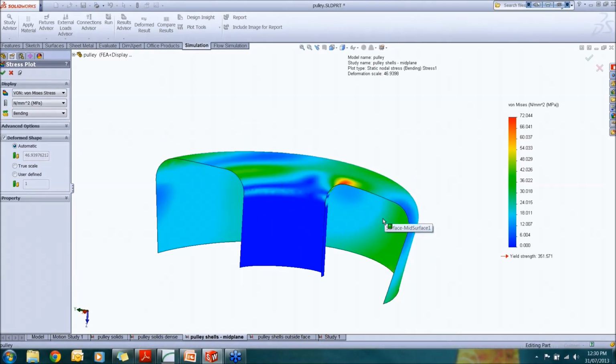So simply, we have put our shell elements somewhere in the middle, and the software calculated the stress values on the top face, bottom face, and calculated the bending for us. This is instead of having 3D elements all going through the bodies and probing the result and making unnecessary refinement to capture the events through the thickness. So 2 seconds and fairly the same option and same result.